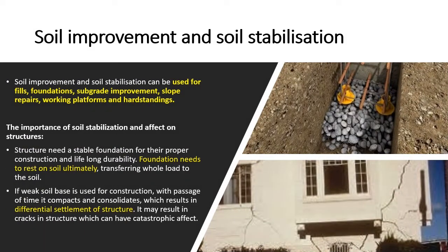Importance of soil stabilization. Structures need a stable foundation for their proper construction and lifelong durability. All the loads coming from the structure will be transferred to the foundation, and the foundation needs to rest on soil, ultimately transferring the whole load to the soil. If a weak soil base is used for construction, with the passage of time it compacts and consolidates, which results in differential settlement of the structure. It may result in cracks in the structure, which can have a catastrophic effect if the settlement is too much.